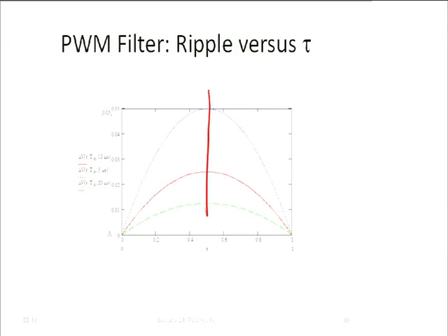What's the disadvantage of making the time constant very long? Longer to get to the steady state. Yeah, exactly. Of course, if the microcontroller wants to switch to another output voltage, then the output eventually will get there, but it's going to take forever for the capacitor to be charged to that new value. All right? So these are RC circuits. They're very useful. And some examples of that.